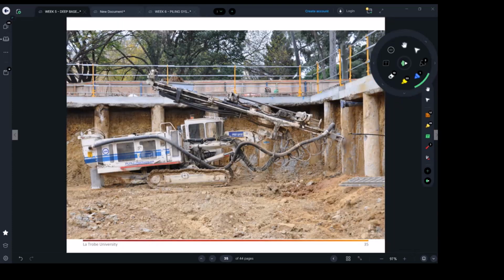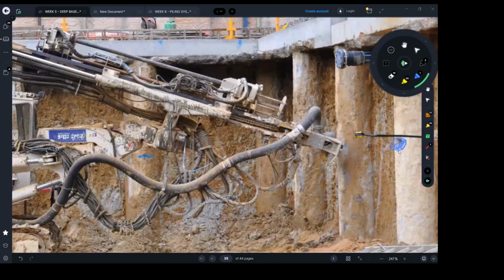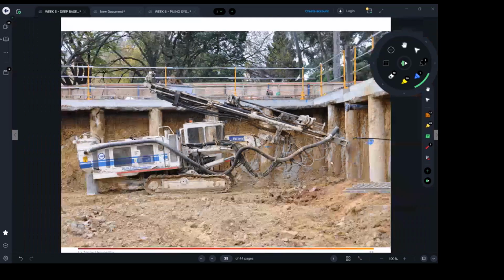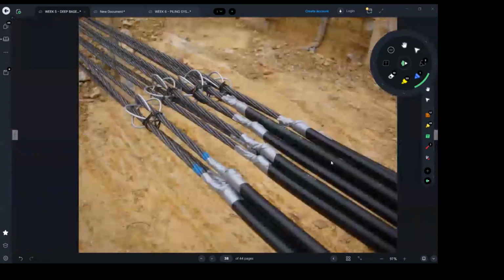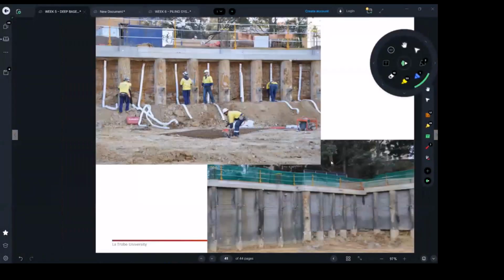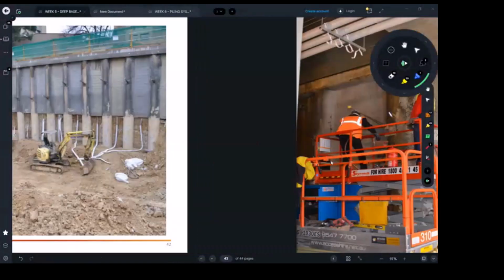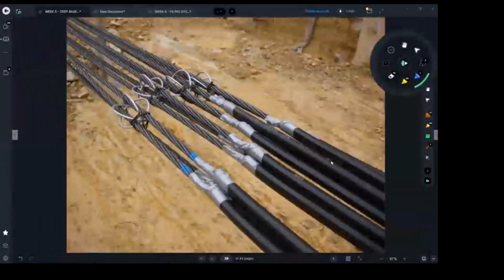Yes, this is how they're going to inject and put the nails, which we will talk about next week. They are here in the process of digging this hole. I told you there's a special equipment which will inject a cable and the concrete. This is really very specialized equipment which will excavate through the pile and 7 meters into the soil, then inject a cable, then inject concrete, then do the retensioning. We will talk about this next week. So I think here we started. Yeah, we do have some good pictures to talk to you about. So I will go through those pictures